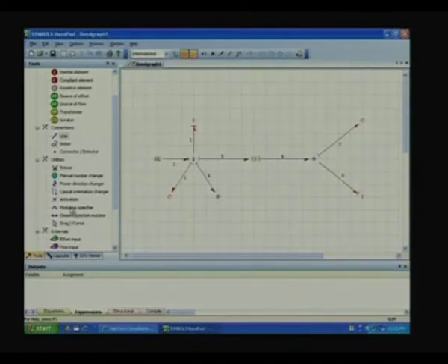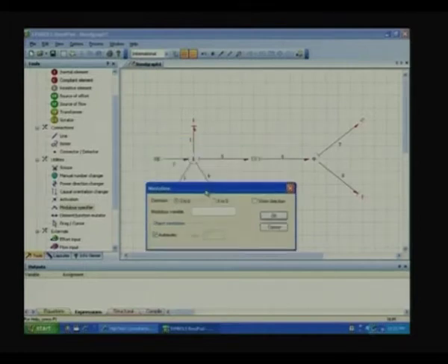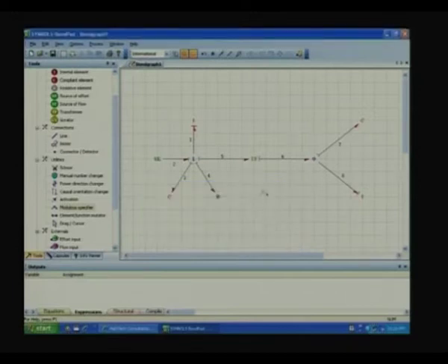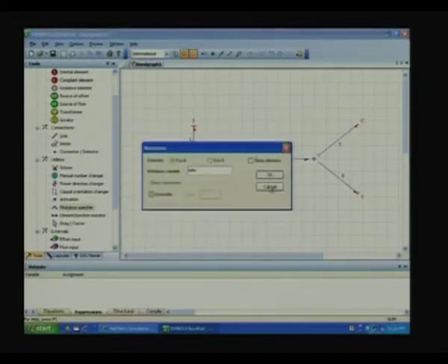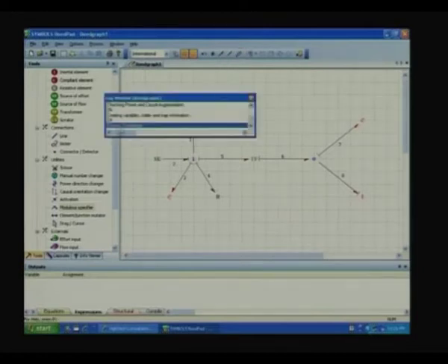Here is an icon called modulus specifier. So, I go on the transformer and click it. It asks whether the direction is 5 to 6 or 6 to 5, obviously, because whatever you are specifying, it could be this way or that way. I say 5 to 6, then I simply write ratio. So, that is the ratio between this side and that side, that is fine. So, it has gone this side, it has already taken it. Now, I check the integrity, it is fine, 0 errors, 0 warnings.